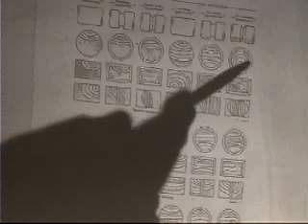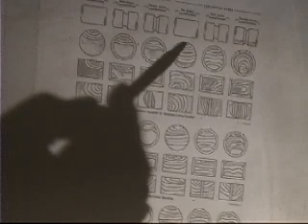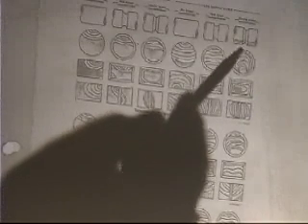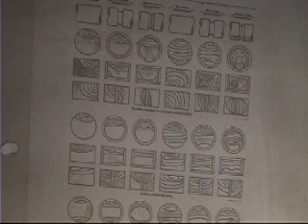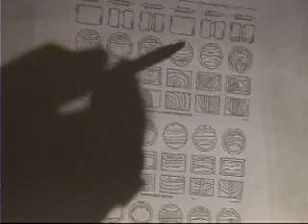You actually will have multiple origins. Typically, on something like this, you'll have a single origin, and everything grows from it. On something like this, you may have 100 origins around here because they're all originating at the stress concentration. When you don't have a stress concentration and you don't have high stresses, it usually initiates at some defect or something. So this either had a defect. If I can't find a defect, then it saw some unusual stress somewhere in its life.